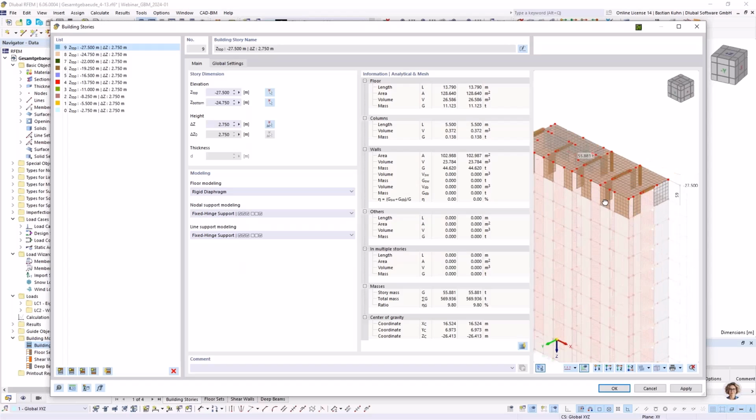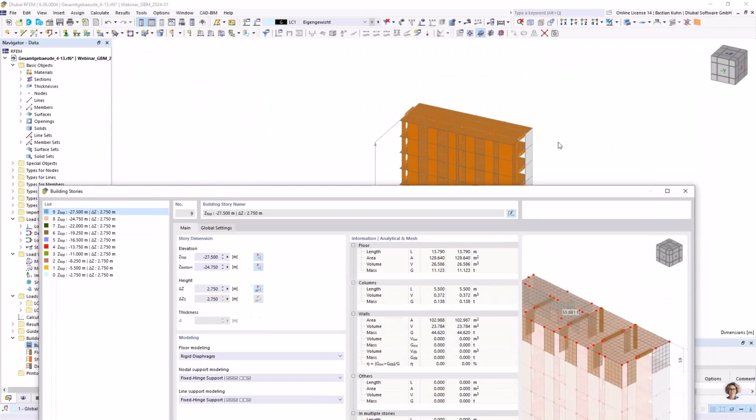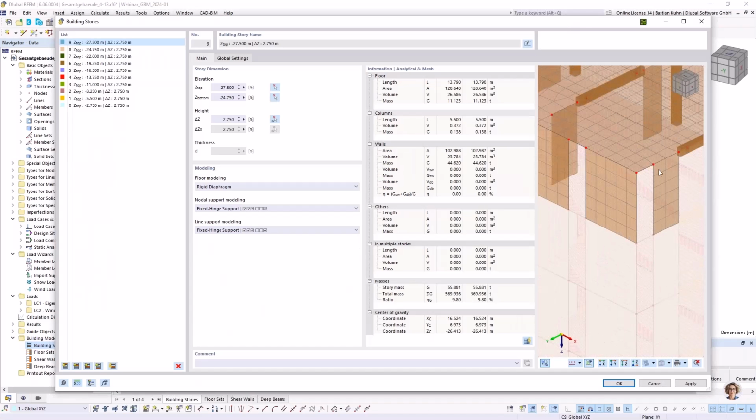Right now, and also in the 3D calculation that I showed you in the start of the building, every FE element has the stiffness of the material, E modulus with the thickness. This gives you the vertical stiffness of it, E by A. And of course, this, as I said, will not regard assembly points or effects.